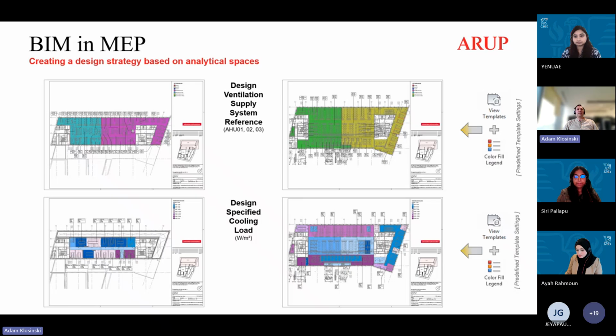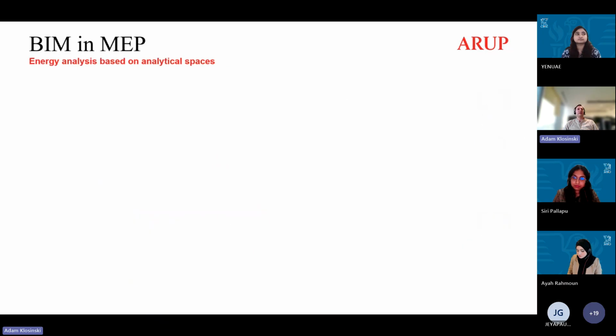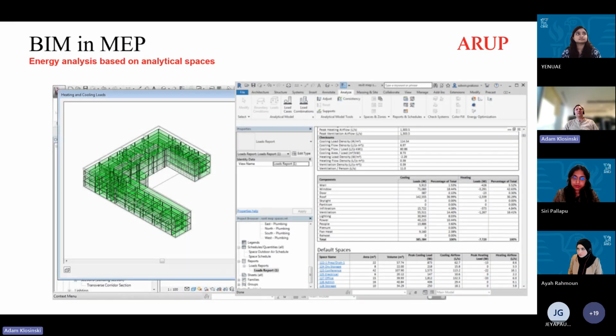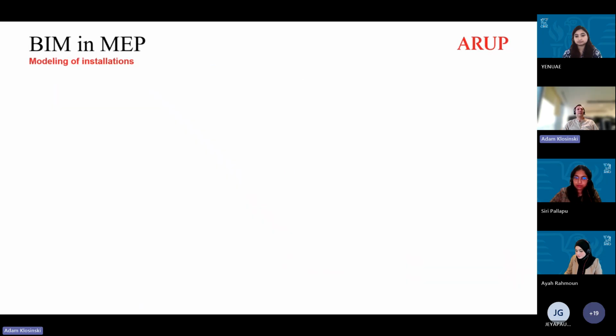This is just another example of the splitting of the whole of the systems which are involved. The other side, which is very often described as BIM 6D, is about energy modeling. So once we've got the appropriate architectural model and the appropriate mechanical MEP models, we are also able to do some energy calculations to predict what the cost of operating the building would be in the future as well.